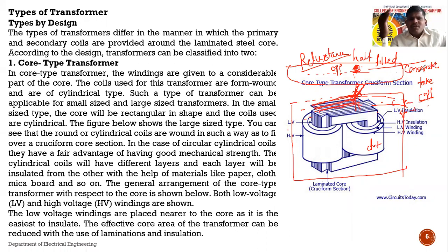So like that, for other equipment, if the transformer is big, there is some cooling method or cooling equipment that can be used. Cooling equipment like a fan, or it may be an air cooled transformer. Sometimes it is a force cooled transformer, sometimes a radiator cooled transformer. You will study this part in your third year in the electrical machine design subject. Okay, so this is related to construction.